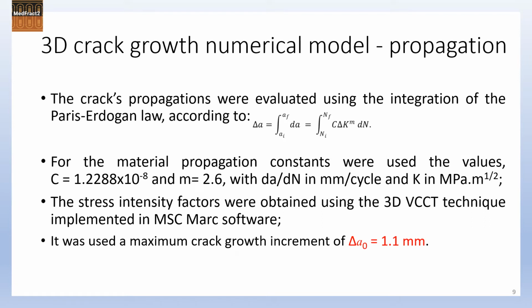The crack propagation was evaluated using the integration of the Paris-Erdogan law. The material propagation constants were obtained in previous work. The stress intensity factors were obtained using the 3D VCCT technique implemented in MSC Marc software. It was used a maximum crack growth increment of 1.1 millimeters.